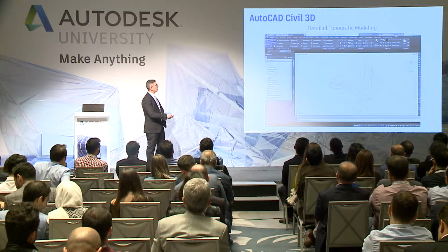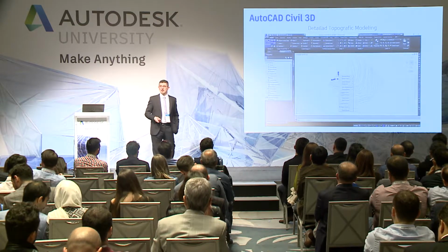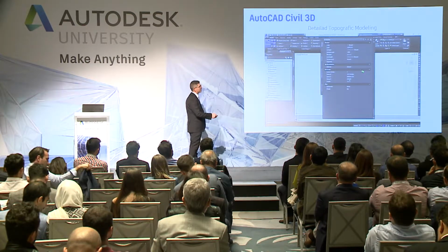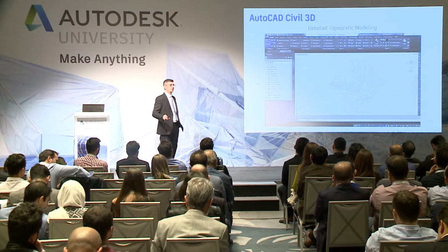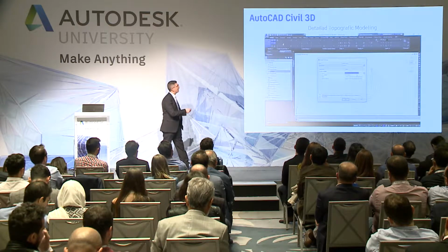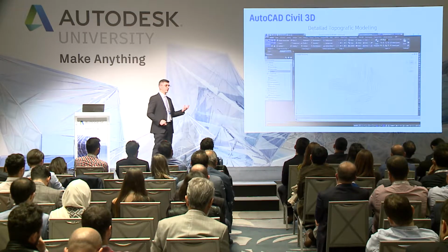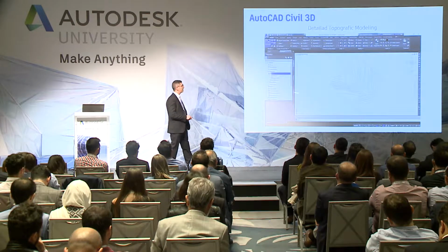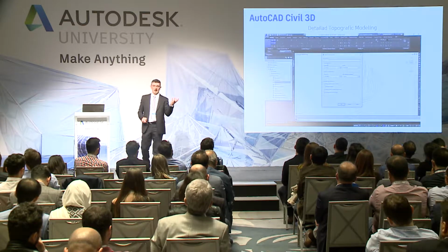Inside Civil 3D, we have the possibility to create a surface starting from many AutoCAD or many data sources. In this case, I can set that it's a 3D polyline. Then we need the 2D and the elevation. Normally we work from this palette. It's a tool space. It's like a tree of objects. It's like Revit, where we need to manage all the objects that we can create. In this case, I started to create the existing ground in a sort of empty box.